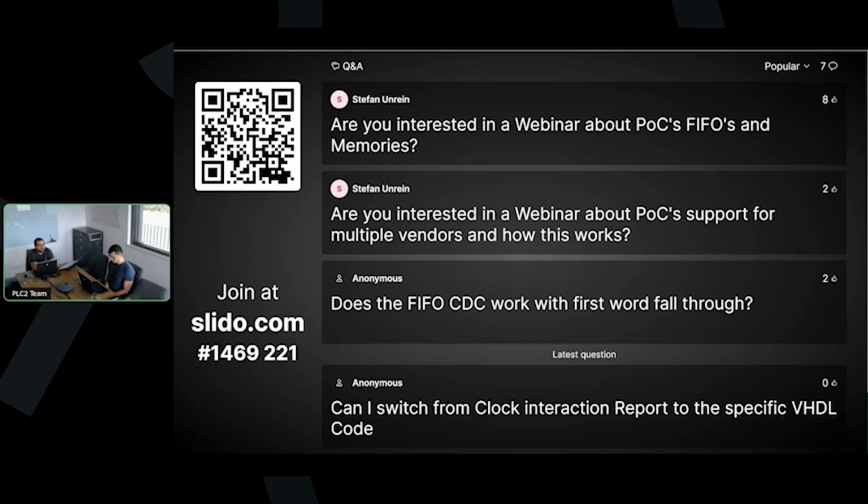Usually what could happen is if you go to the normal timing report, so run timing analysis or timing report, you have the interclock settings or interclock drop downs, and then there's the intraclock where we have, let's say, from 100 to 200 megahertz. If you open this one, you see where you have maybe failing timing constraints or even ones that are good. And you can check if you find timings, let's say, of 2 nanoseconds, which you don't have as a constraint and no frequency that's so high. That's an indication that there's a constraint missing. So if you have weird numbers, but it's not yet failing, that could be one. Do you have any other idea, Stefan?